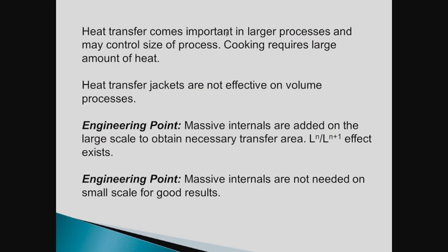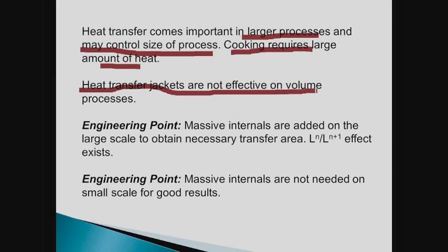Heat transfer becomes important in larger processes and may control the size of the process. Cooking may require large amounts of heat, for example. We also find that jackets are not very effective on volume processes, i.e., as you scale up, the heat transfer jackets become less important.